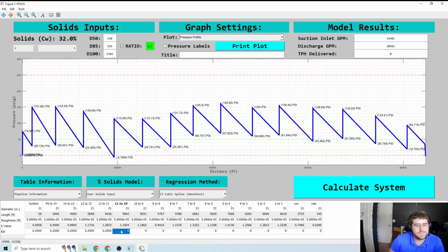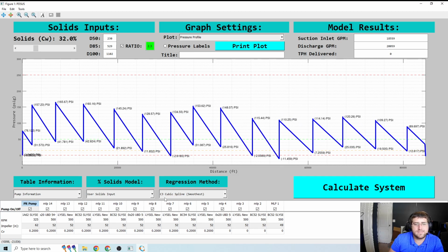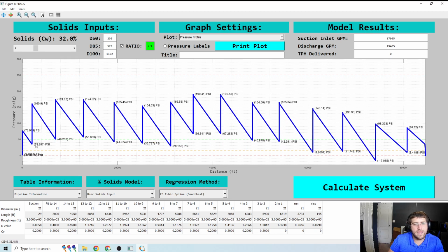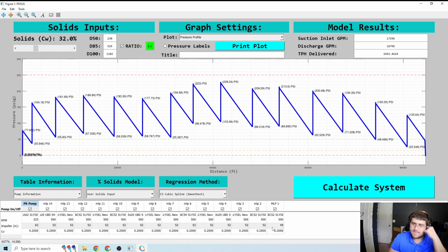You know, we're seeing kind of the truth behind maybe some of the problems that you can see in an inconsistent feed and long slurry pipeline coming to a head here. So now I go all the way to 5. All right, solids work their way. Pressure's recovered here, but now they're dropping in the middle, right? Okay, solids are, let's say they work their way all the way to MLP2. Okay, now the pressures on the suction end are recovering, but we're still a little low on the discharge end. And finally, as these solids come through, we're back to something more normal.